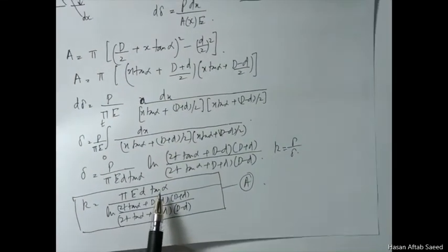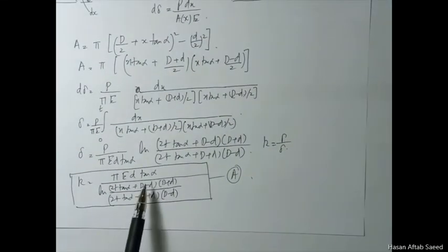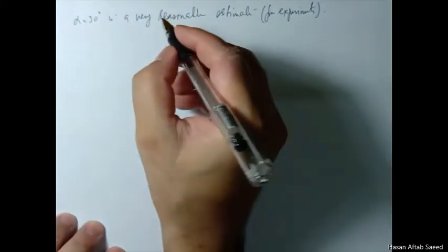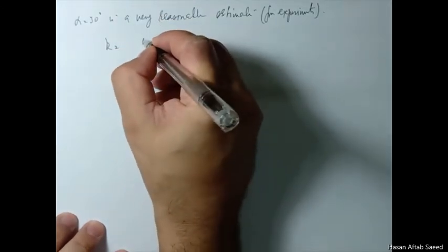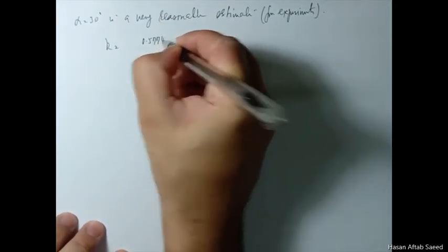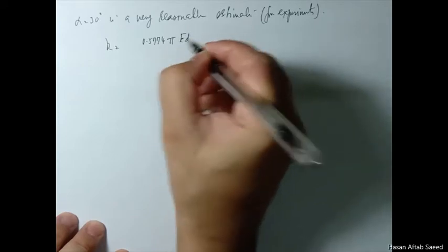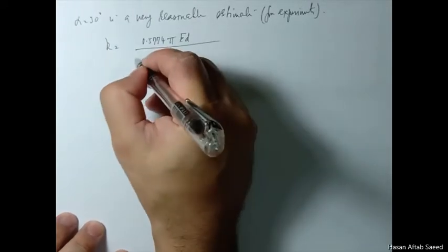Obviously it won't be exactly 30 degrees, but 30 degrees is not very far off, and FEM studies have also confirmed this. So if you use alpha equal to 30 degrees, you can simplify it further by reducing one variable. And this k turns out to be, for 30 degrees, as follows. Now this is a special case, but it is very close to the true situation.